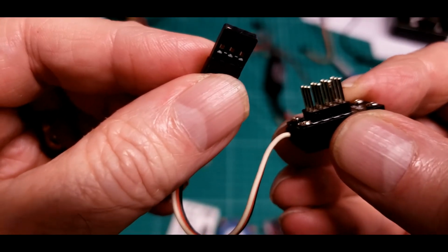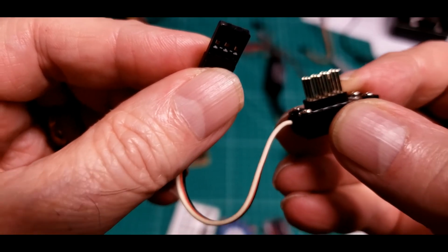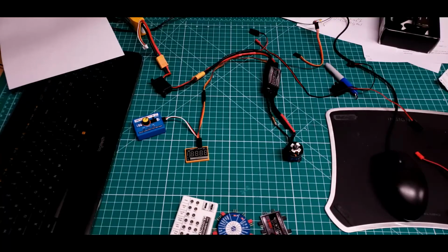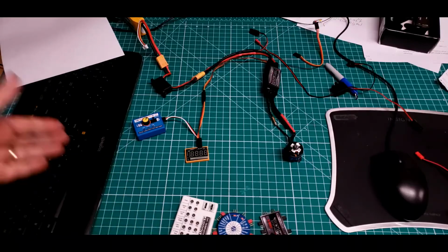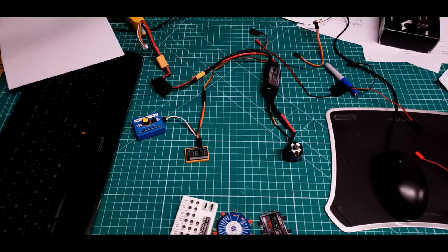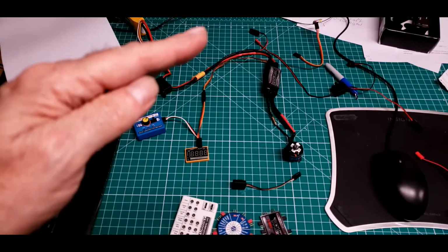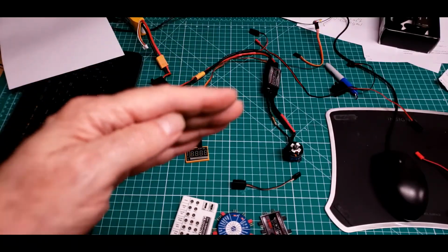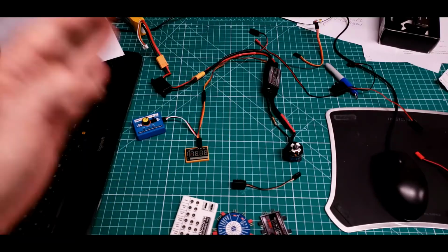The pulse width on your radio and your receiver is not going to change. You can take 4 ESCs, program 1 on your receiver, disconnect it, put number 2 on there, program it, disconnect it, put number 3 on there, program it, put number 4 on there, and program it. You're not changing the electronics you're using to produce that pulse width, so what you're using is going to be consistent and the same each time. And you're going to successfully program all 4 of those ESCs with the high throttle pulse width that your radio is going to be forever giving it, and for the low.